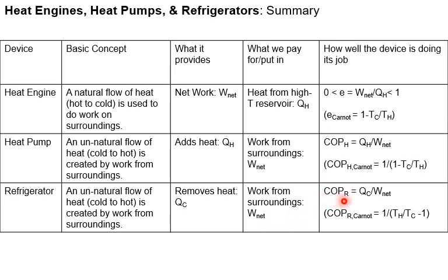That's defined by the coefficient of performance. So that's how much heat you're sucking from the inside of the fridge, from the food, divided by the work that you're putting in, for instance, via electrical energy. And the optimum performance, again, is Carnot. And so here you have 1 divided by the temperature of the hot reservoir divided by the temperature of the cold minus 1.